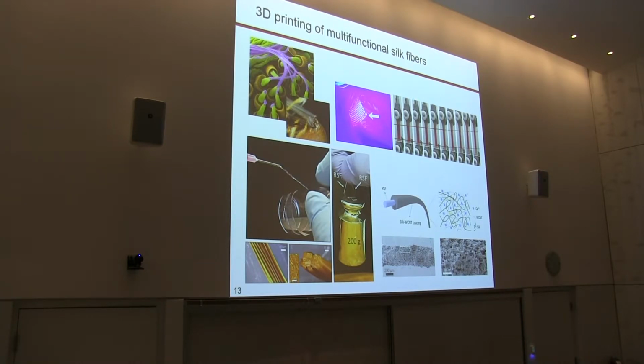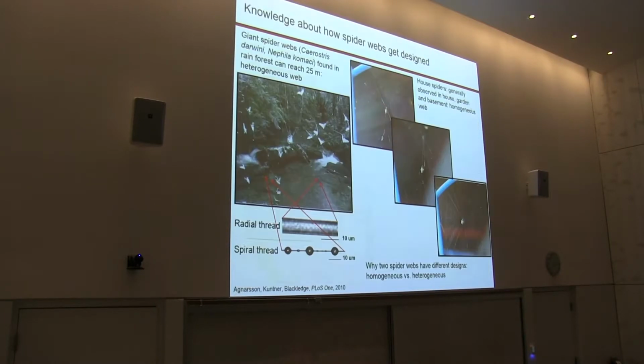It also has a porous surface and is very easy to absorb humidity, like the water from the environment. Once it absorbs water, the resistance of the fiber can change. So it can be applied in sensing to detect humidity change inside the environment.